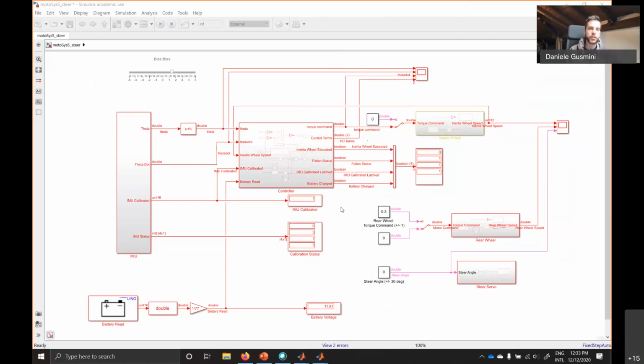Since this wheel is rotating, each time a magnet passes in front of the sensor, we register a presence, and so we can understand the speed of the wheel through the computation of the time between one sensing and the next. I hope that now it is clear.